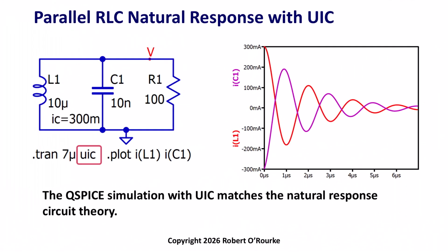When a UIC statement is present in the QSPICE transient simulation, the QSPICE simulation correctly matches the circuit theory of the natural response due to the instantaneous initial condition inductor current all going into the capacitor.